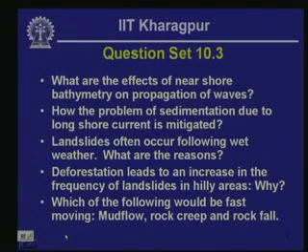The third question that I asked was this: landslides often occur following wet weather. What are the reasons? Following wet weather, typically two things happen. One is that the water table comes up to near the slope face, and that may lead to egress or daylighting of the seepage near the bottom of the slope, and this may cause erosion. So erosional instability is likely to cause landslides. That is one of the aspects.